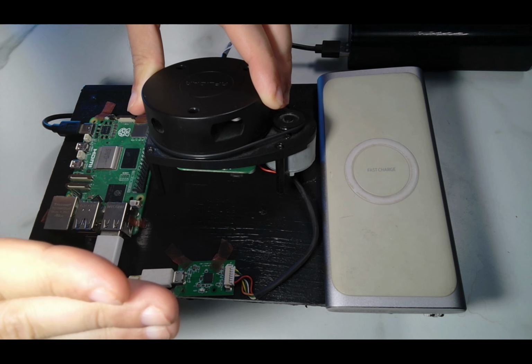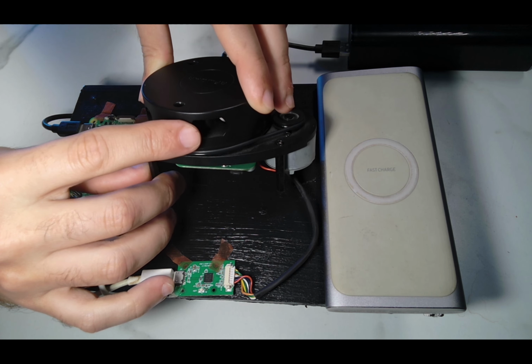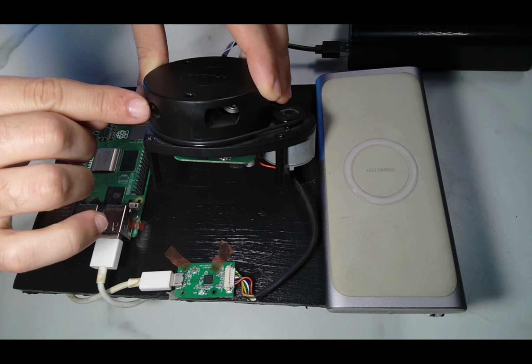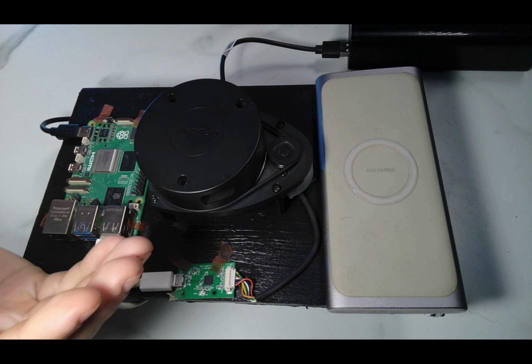Whenever it reaches some object, part of the energy is reflected back, and this energy is captured by this other sensor here. So this is actually not a sensor, this is a light emitting diode, and this is a light receiver. Because we know the speed of light and the distance that the mechanism has, we can factor out with some equations the total travel distance. We call this time of flight. And then we can tell almost exactly the distance to the object.